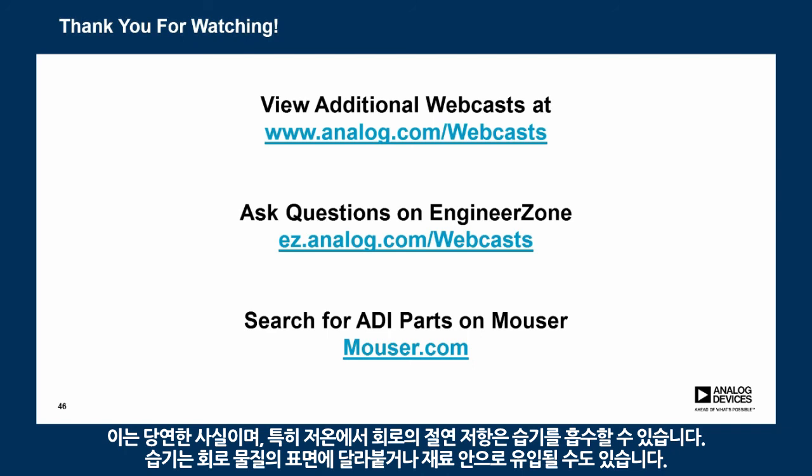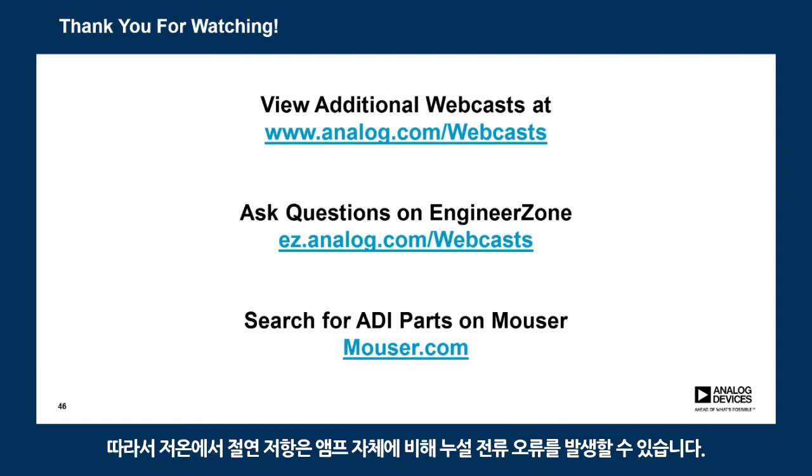The insulation resistance of the circuit material can absorb moisture. Moisture can either adhere to the surface of the circuit material or enter the bulk of the material. So at low temperature, the insulation resistance could actually create more leakage current error compared to the amplifier itself.